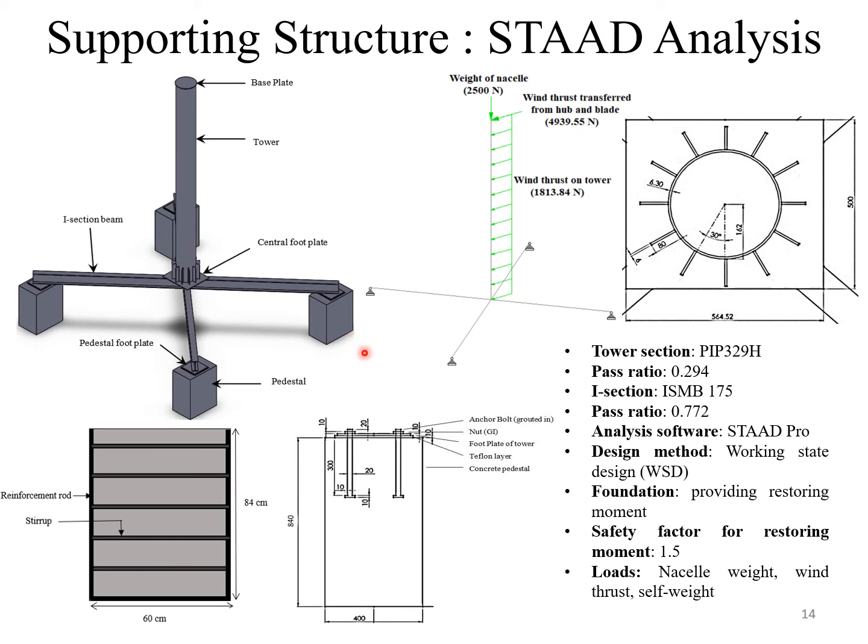Since the rooftop surface cannot be grouted, it is important to provide a sturdy pedestal foundation on which the tower can self-sustain against extreme weather. Vertical reinforcement steel rods along with 5 layers of horizontal stirrups are provided for supporting each of the 4 M20 concrete pedestals. The monopole tower is welded to the central footplate and reinforced against bending moments by the buttresses, which provide large bending areas. The central footplate is welded to the I-section beams, which are in turn bolted to the footplates on the concrete pedestal.